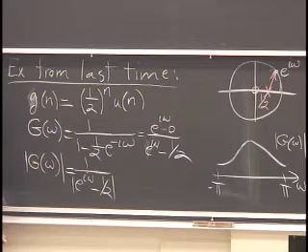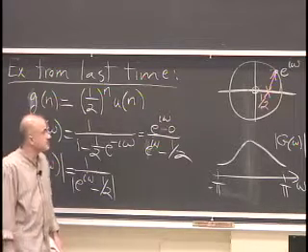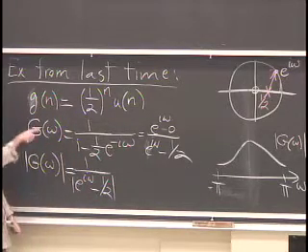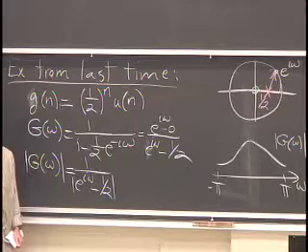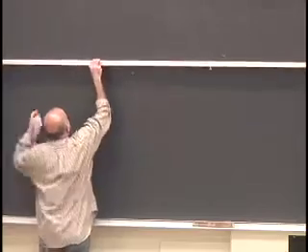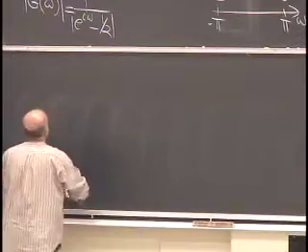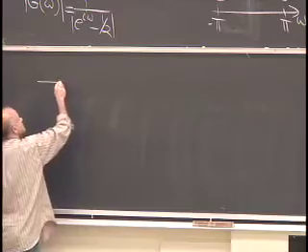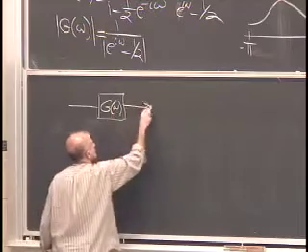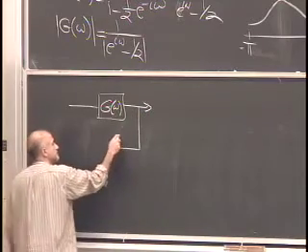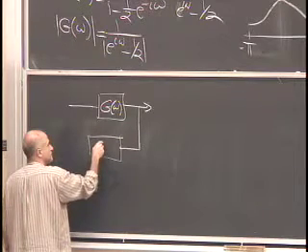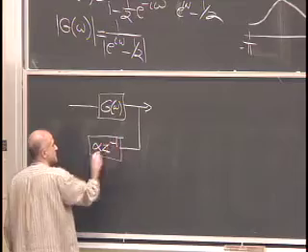Now, how does feedback come into the picture? Suppose you've built 1 million of these gadgets, and your boss tells you, OK, I want a high-pass filter. Can you build me a high-pass filter in a way that we won't let these go to waste? You say, sure. Let's see if we place that system in a feedback where the feedback is, I'm going to denote it this way, alpha z to the minus 1.